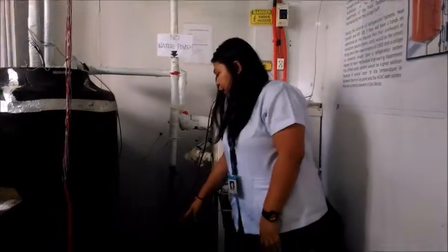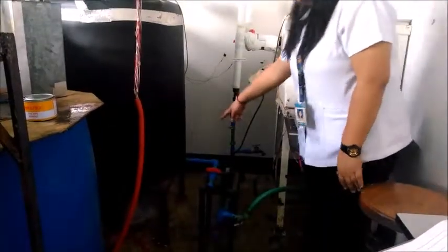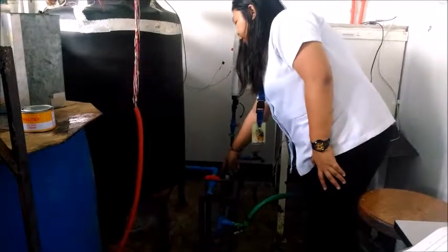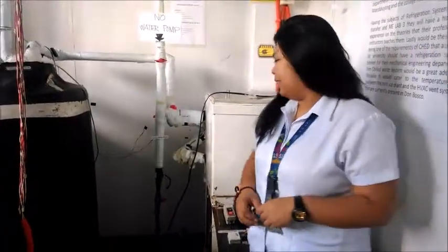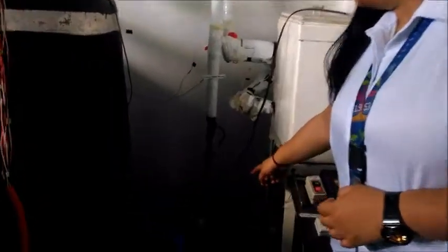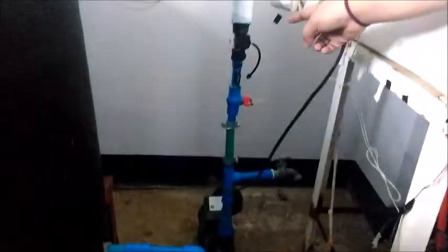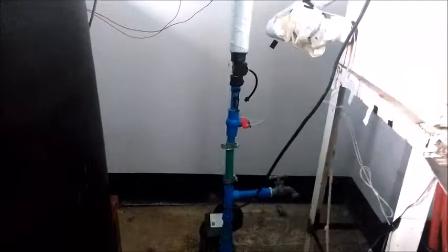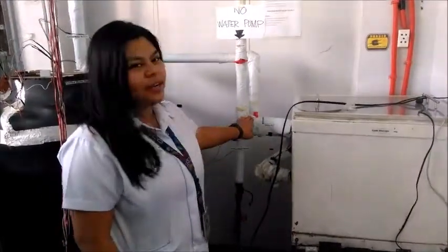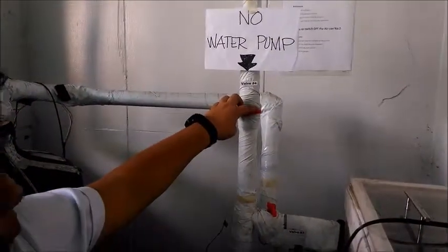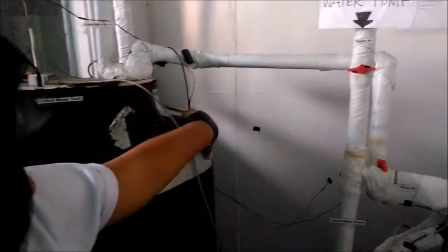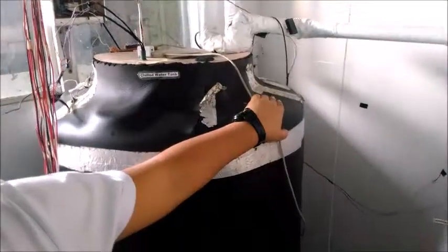The fan coil unit. To operate the fan coil unit, first, we must change the state of the valve located right after the discharge port of the chilled water tank. We should put it in fully open mode. Next is the valve located between the discharge port of the pump and the flow sensor. Put it in fully open mode. Without opening valve number 3, you must turn this valve number 4 to fully open mode in order for the chilled water tank to fully flow onto the fan coil unit.